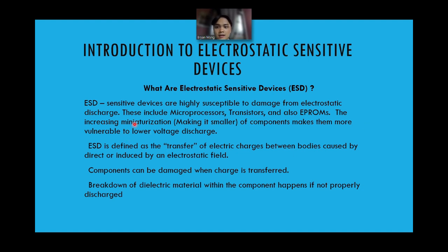The increasing miniaturization means making the components smaller, which is tiny, small lah. This makes them much more vulnerable to lower voltage discharge. Due to them being very tiny, they are much more prone to voltage discharge lah. ESD is defined as the transfer of electric charges between bodies caused by direct contact or induced by an electrostatic field. So this is how ESD is transferred.